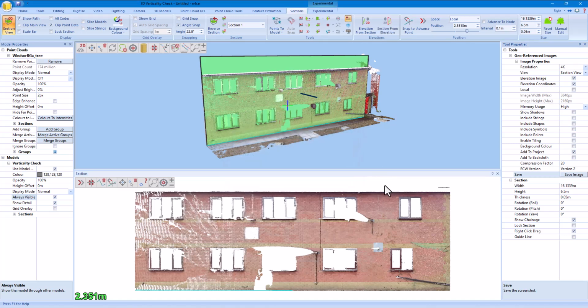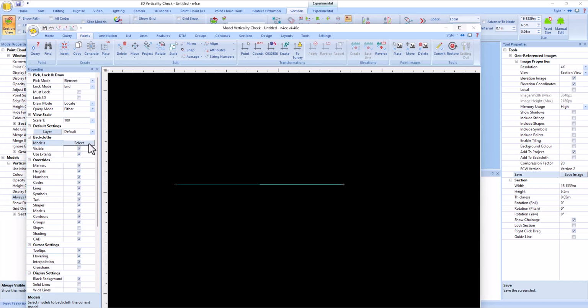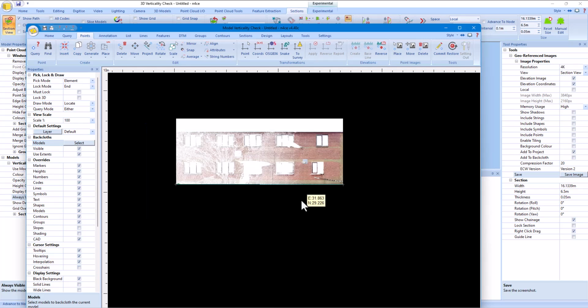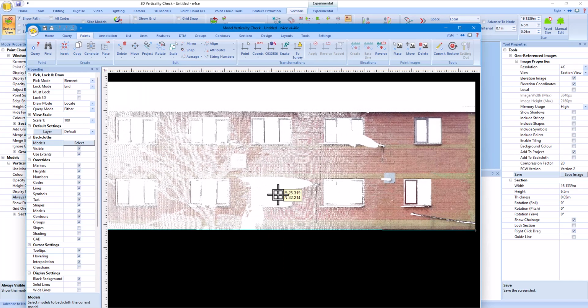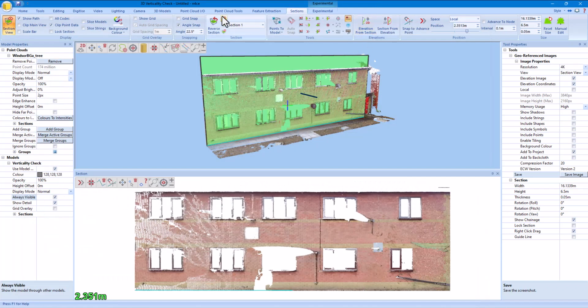This flips the 2D model into the same coordinate system as the section, so we are now viewing it from the side. We can now test the image lines up with the baseline by back-clipping it into the model view. That all seems to line up, so we can continue to extracting some points over the surface of the wall.